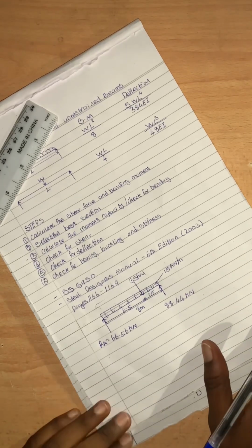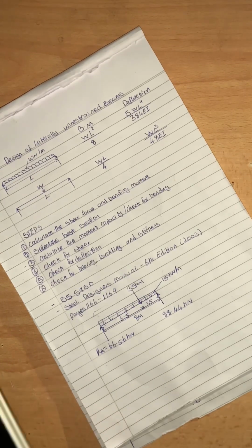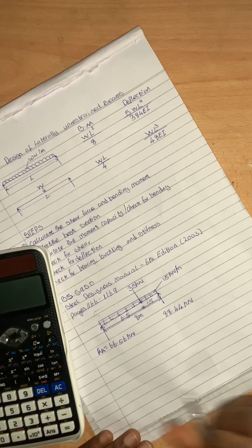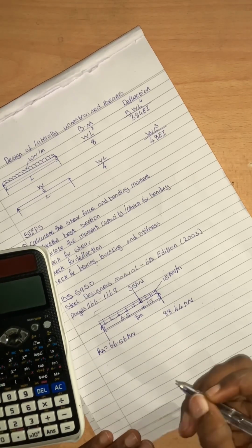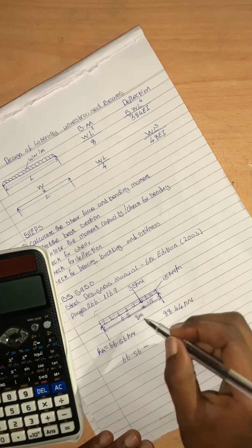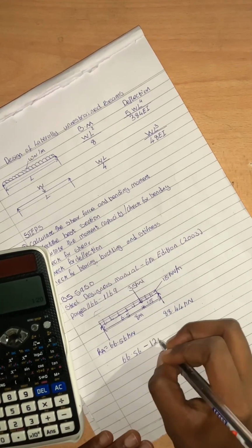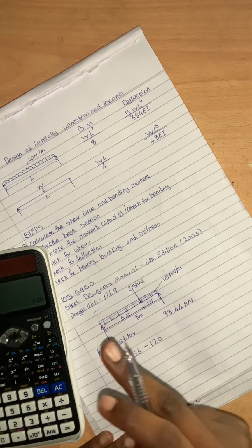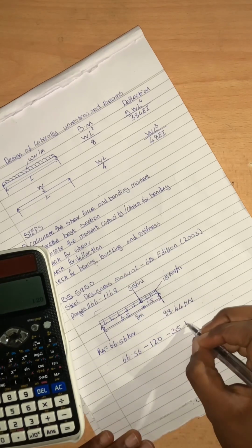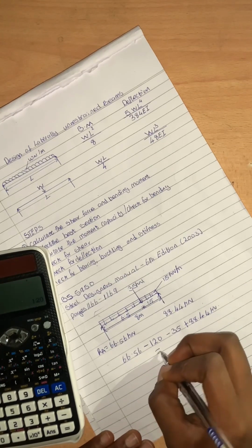So I'm just going to show you how to calculate the shear force and bending moment diagram. But just a quick recap: how do you know that your reaction is correct? You can do your reaction check. It's just my way of doing it quickly. That's 66.56 minus 15 times 8, because this UDL is throughout the length. 15 times 8 is 120, minus 120. This is negative because it's going down. This is positive because it is going up. So minus 35 kilonewton, and then this is going up, plus 88.44 kilonewton. So this should all sum up to give us 0.